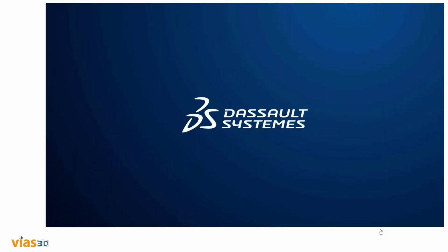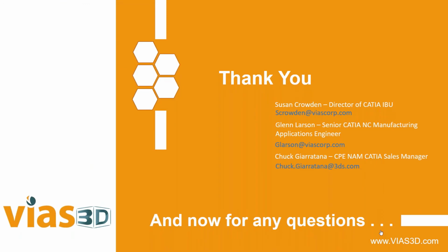Thank you, Glenn. We have another question from the attendees, which says, what is the difference between Abaqus and Simulia in regards to how everything comes together? Is Simulia preferred due to native format? Well, that's a really good question. As we've gone through time, in the beginning, there were things in Abaqus that they didn't have in Simulia on the platform available yet. So there were reasons to use Abaqus. But every year there's less and less, Simulia covers all of those bases. So I find Simulia to be the preferred method, but you can run any Abaqus command from Process Composer.